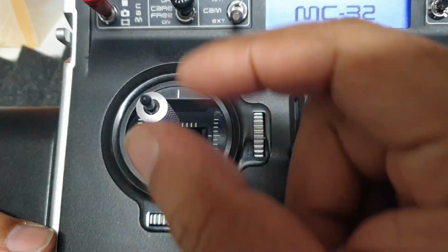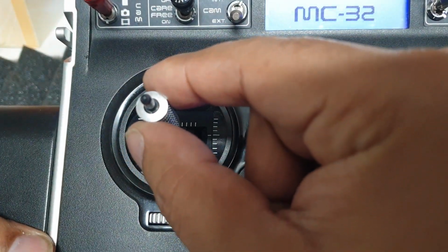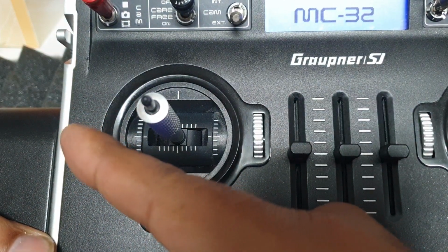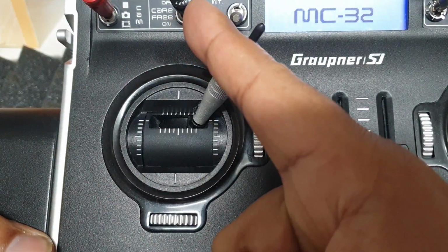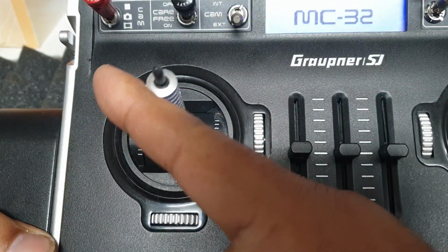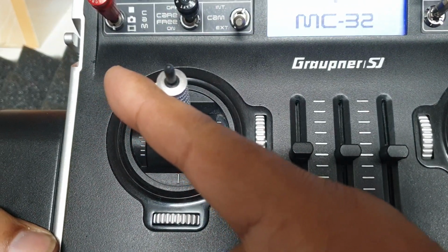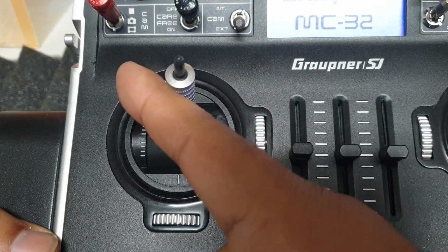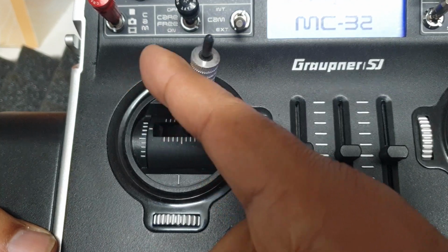So let me go one step back. Let's say this is a fixed part and this is not moving. This is solid, okay? Now, if I move 150% of my servo, this is where it's going to go. But because this is solid, my servo is constantly pushing against this thing, which is not bringing me any value, because my servo is pushing this lever because it wants to travel further.